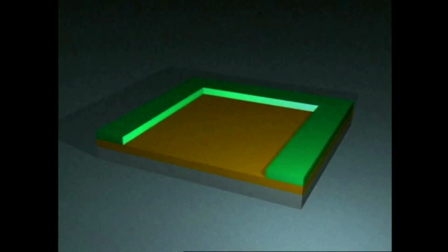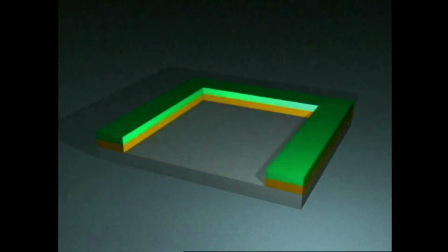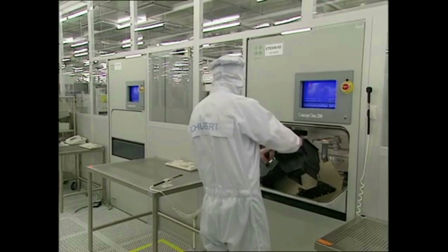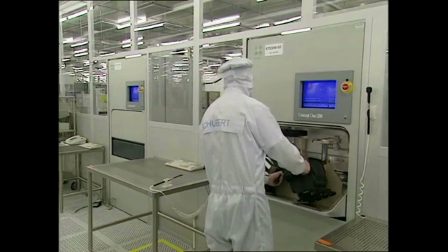The oxide layer is etched. This etching process is carried out either by wet etching or plasma etching. In plasma etching, special gases combine with the layer to be removed. This makes it possible to remove the microscopically thin layers inside the windows created by exposure, development and etching.